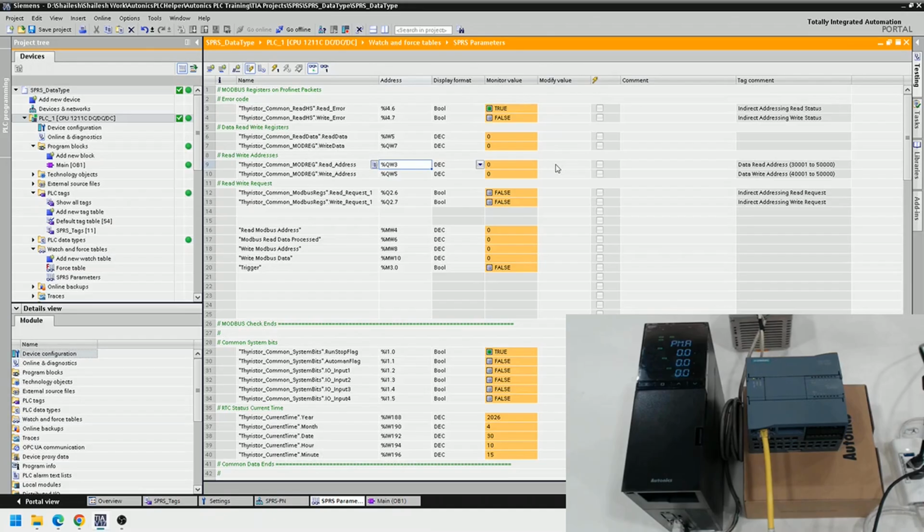It will not accept the same 41441 over here because it reads the data in a swapped byte, a different endian format. So I'll put the read Modbus address over here, 41441, and give a trigger to send it. This is an internal trigger. Now we can see that data has flown, so this data 41441 in a swapped byte is this. Now this is the correct format.